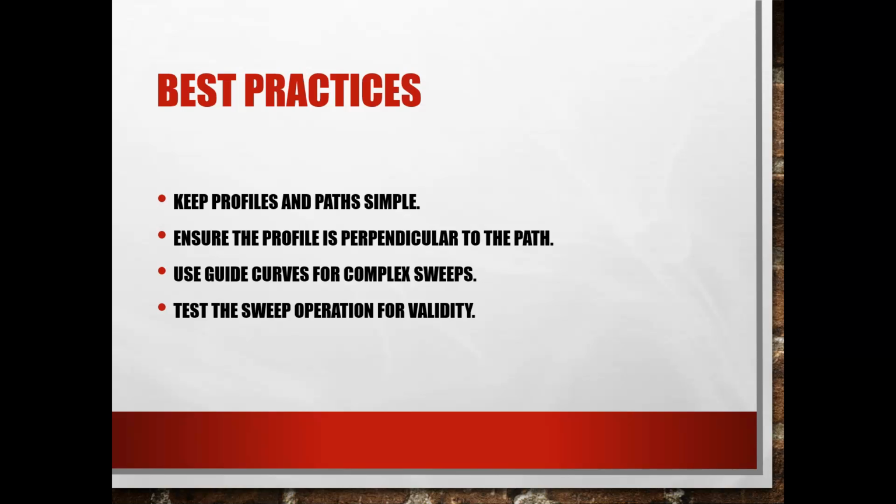All right. I already mentioned to make sure that the path is perpendicular to the profile. You're going to get that by default. Just make sure whenever you're creating those planes that you have that in mind. All of that is going to be created naturally, especially in SolidWorks and Inventor. In AutoCAD, you're just going to have to use the gizmo and rotate either your profile or your path to fit whatever you want.